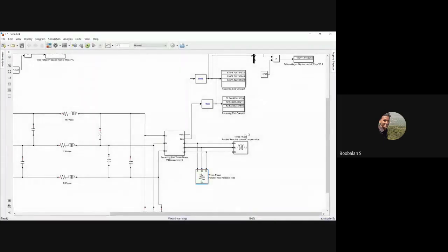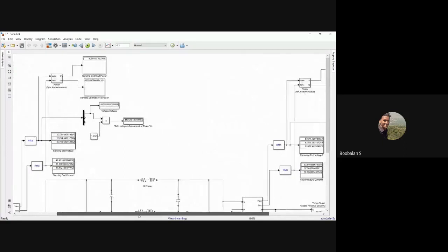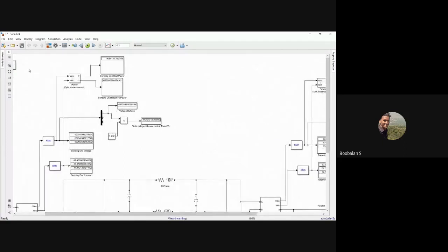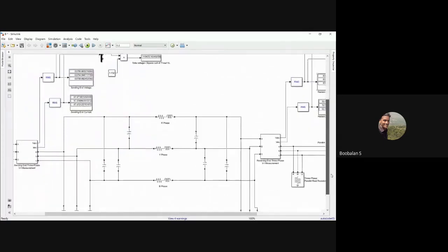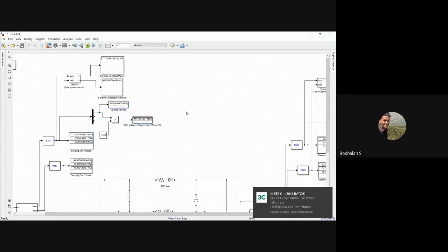Yeah, right. Now the load is also connected, and the reactive power also connected. Now it's time to calculate voltage regulation as well as my transmission line power efficiency, right? So what is the formula for calculating voltage regulation? The voltage regulation formula will be very easy, right? Sending end voltage minus receiving end voltage, divided by sending end voltage, into 100 percent, right?